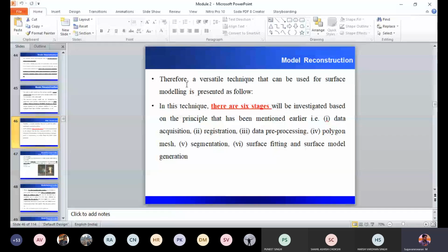So obviously, if you move from point to line, line to sheet, the cost will also increase. But at the same time, your accuracy and data capturing will be enormous if you use a sheet of laser compared to point laser. In point laser, for each and every point on a surface, you have to pause and measure. So the time taken to complete a measurement and data processing will be tedious in point source. So that is what we did discuss so far.